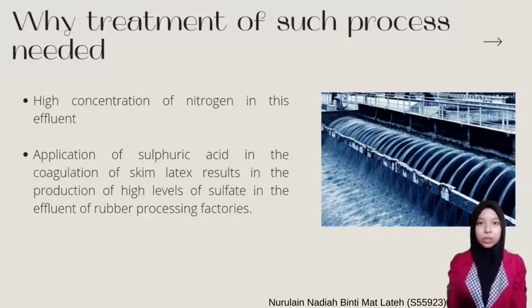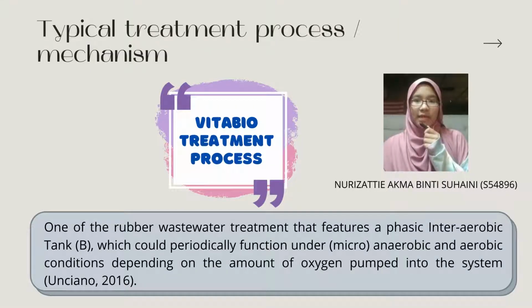Other than that, the application of sulfuric acid in the coagulation of skin latex results in the production of a high level of sulfate in the effluent of the rubber processing factory. The high level of hydrogen sulfide will be liberated to the environment and cause malodor problems. The free H2S also inhibits the digestion process, which gives lower organic removal efficiency. The odor is detectable even at extremely low concentration and makes water unpalatable for several hundred miles downstream from the rubber processing factory.